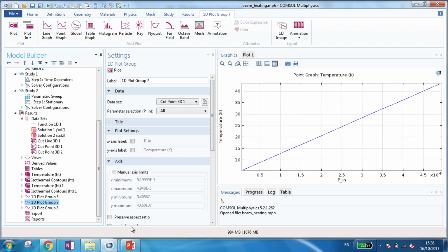Since we are seeing this time dependence for the first time, it's practically a sweep of time. It starts with the initial condition and it just moves the problem further. So what I have done is, if you take this study, it will give you a time range. For example, I simulate from 0 to 500 milliseconds with steps of 6 milliseconds.